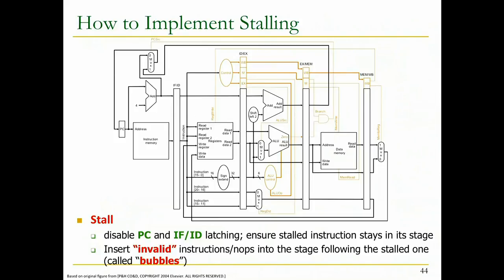So from a testability and design perspective, it's more principled to have a valid bit, in my opinion. Because when you are trying to debug this pipeline, you can check that valid bit. It's a lot harder to inspect all of the contents of the control signals to conclude this is a no-op. Again, you may save a bit, but saving a bit doesn't always save you time later on. So if you think about design for testing this machine, it's always better to have the valid bit over there.